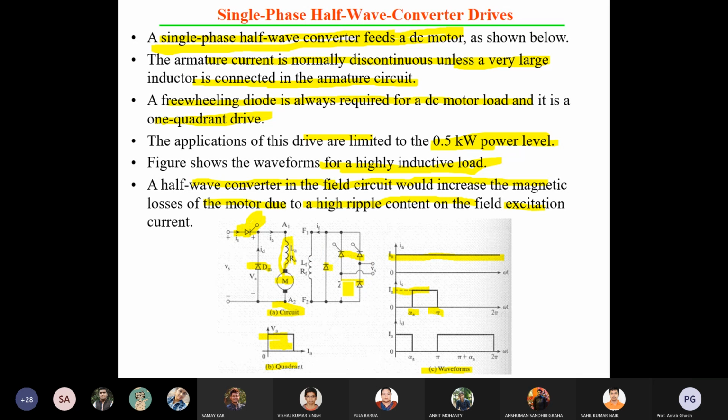It's a semi converter bridge, a symmetrical semi converter bridge, for reducing ripple. In one cycle you can control that SCR, and in both cycles you can control both the SCRs. And you are getting the field voltage here, you are energizing the field.